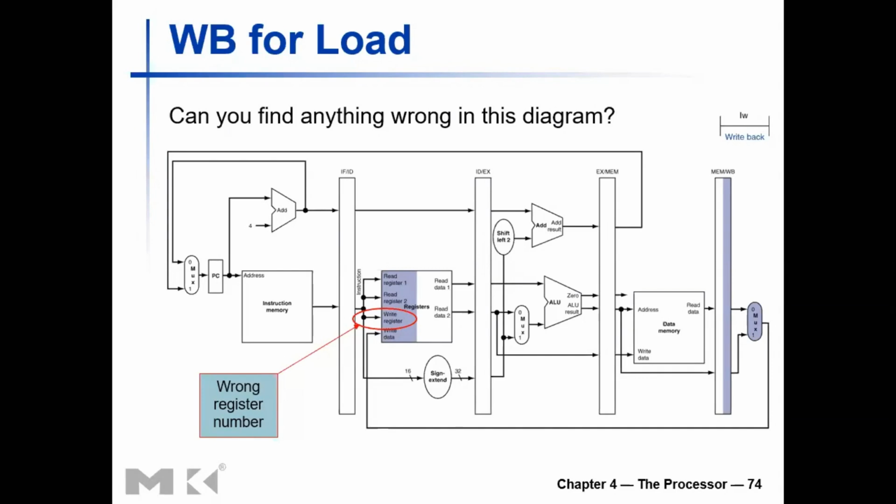I think that what you're thinking about using a multiplexer is okay, it's correct, but without storing the value in the pipeline register, just using a multiplexer will not work. So we will have to store the value in a pipeline register. That is correct.